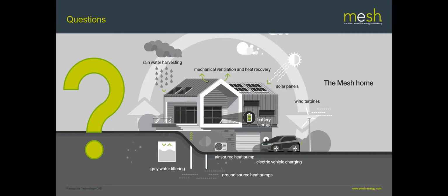Patrick asks, can home generated wind energy be linked to battery storage? Yes, it can. It would be similar to PV, in that, obviously wind generates AC, so you'd effectively have an AC coupled system. You need some sort of power conditioning for it to feed to the battery in a nice way, but it can be done.